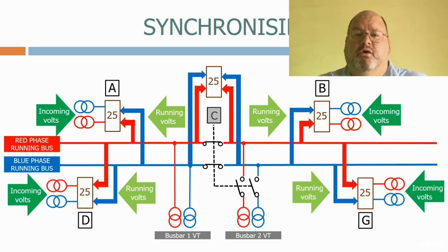Voltage selection circuits in old complex substations can be a nightmare to commission due to the large number of inputs involved. To implement the scheme, we need to make connections to every single circuit breaker mechanism to pick up the auxiliary switches and every single voltage transformer to pick up the secondary voltages. They are also notoriously difficult to modify should we want to change the substation configuration, as every substation seems to have its own way of making the interconnections.